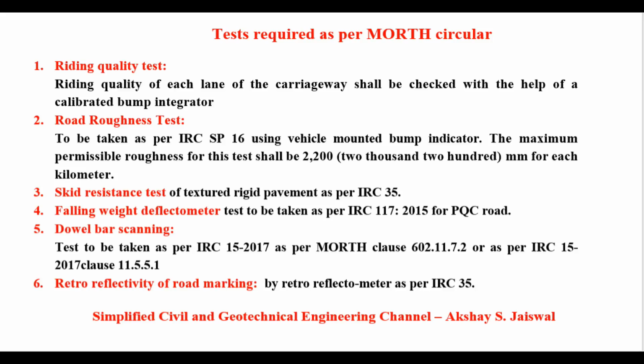Third test is skid resistance test of textured rigid pavement. It is carried out as per IRC 35. Fourth test is falling weight deflectometer test, which is carried out as per IRC 117/2015 for PQC road. Fifth test is dowel bar scanning test. It is carried out as per IRC 15/2017. Last test is retroreflectivity of road marking by using retroreflectometer as per IRC 35.